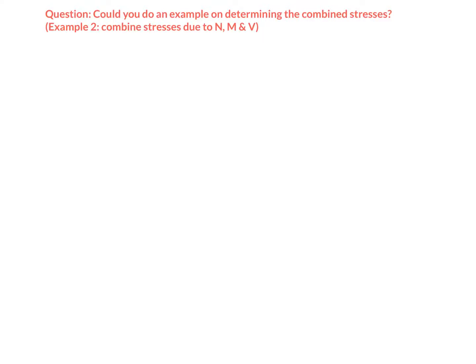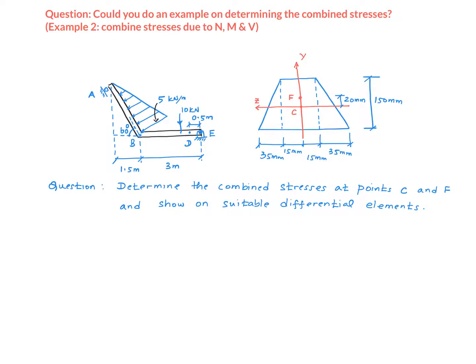The question here is, could you do an example on determining the combined stresses? In this particular example, I'm going to show you how to combine stresses due to the axial force N, the bending moment M, and the shear force V. This is the problem that I have chosen here.